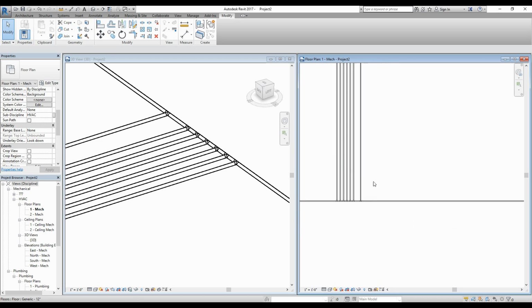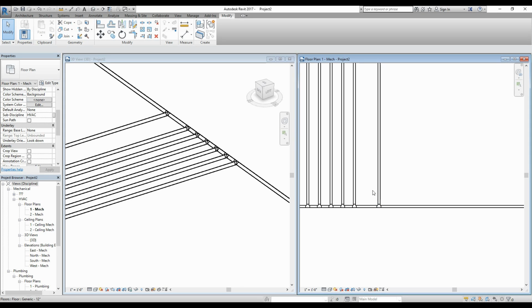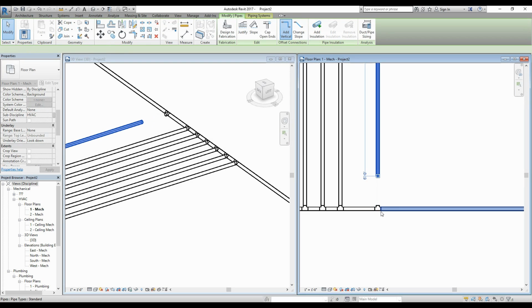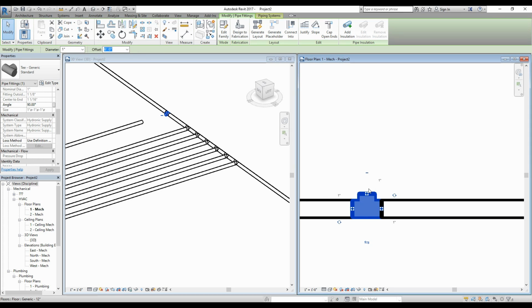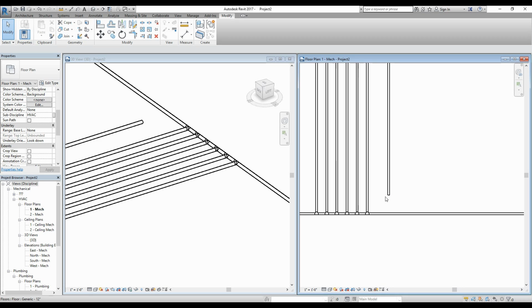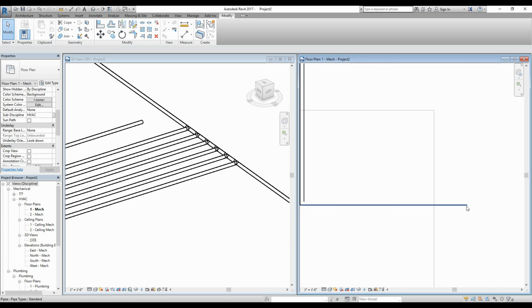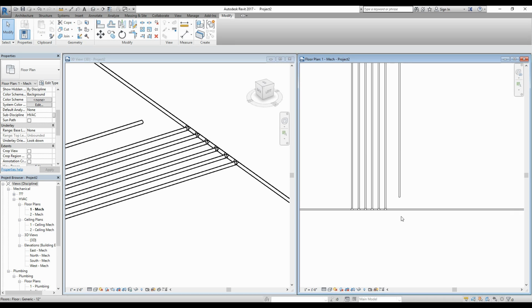Now say you want this pipe and this pipe to connect in a 90-degree elbow. I'm just gonna show you an easy way. I'm just gonna drag this back like we did before. Under these fittings, sometimes they have these little minus or pluses, and this minus will just get rid of this fitting, make it a pipe again. Now I want these at an elbow. I could drag this one all the way back, drag this one to the end, and have it connect.